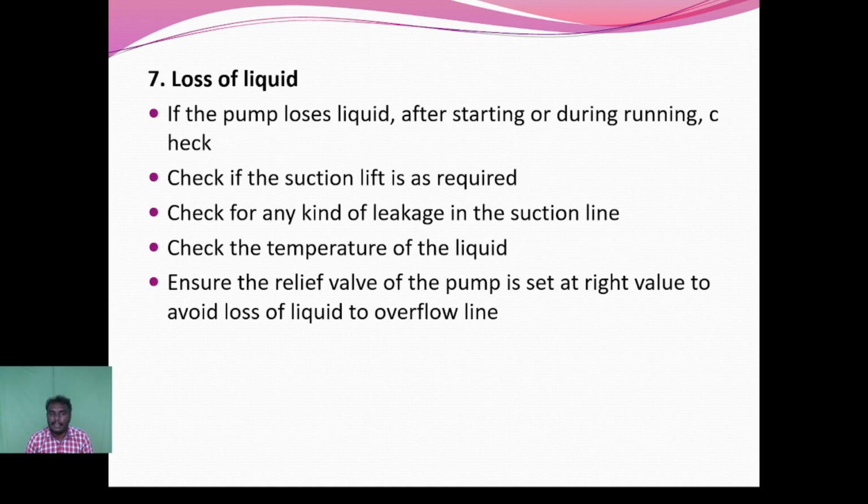The third thing is to check for any kind of leakage in the suction line. Then the temperature of the fluid should be at a medium level; if it is too high, the pipe may get damaged. Ensure the relief valve of the pump is set at the right value to avoid loss of liquid to the overflow line.